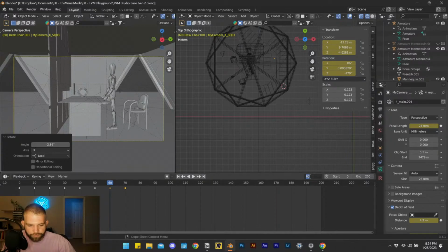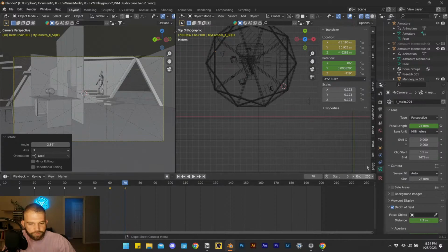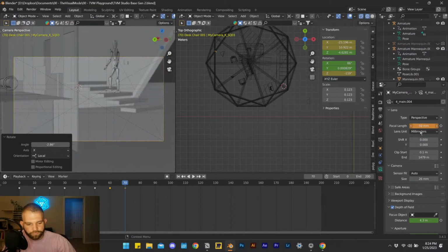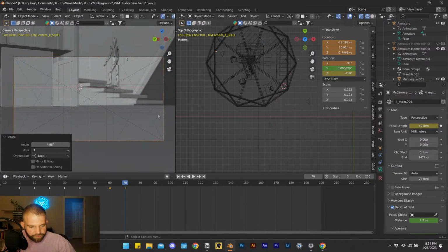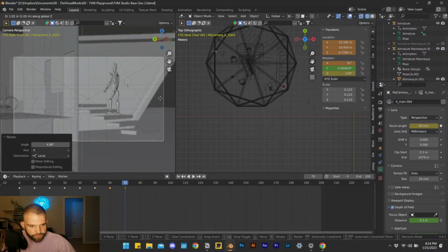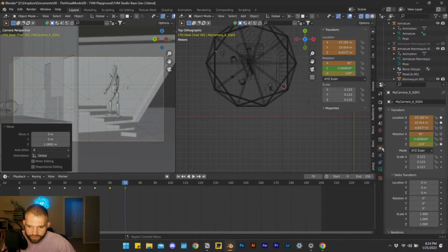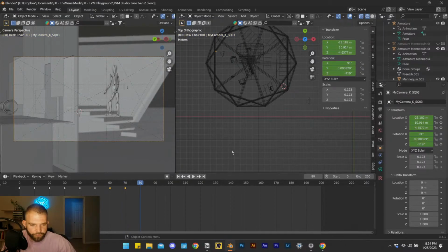We go to keyframe 70. So we see our new one. There we go. And we had this set to 50. So we'll keyframe that. And I also failed to keyframe the camera rotation, it seems. So make sure you keyframe everything. Just be safe. Keyframe everything. There we go. It looks like I didn't keyframe the Z location. All right, we'll save there. Next frame, we got 2 down, 4 to go. Number 80.